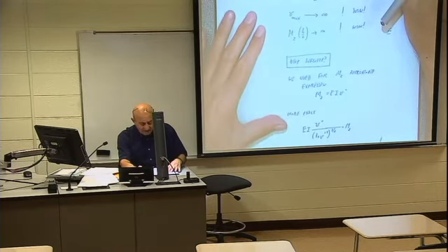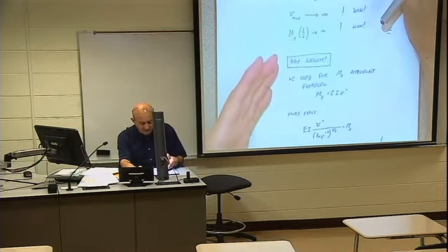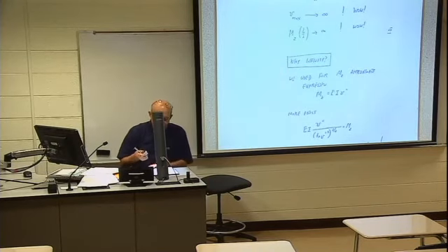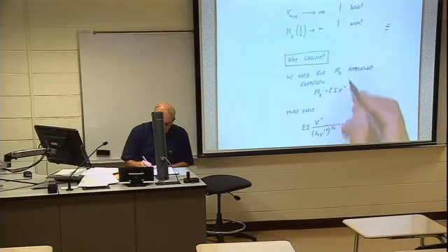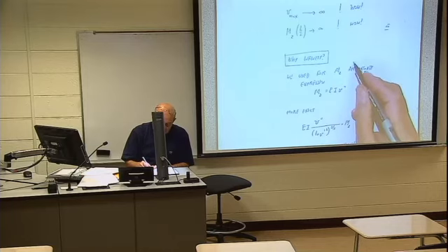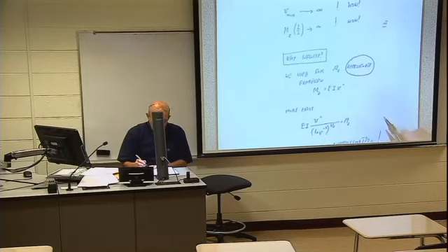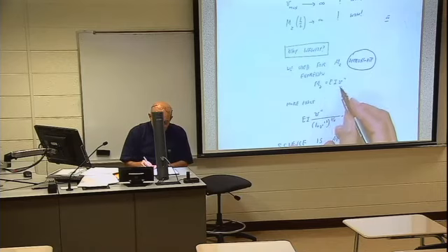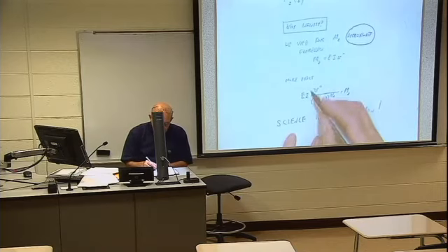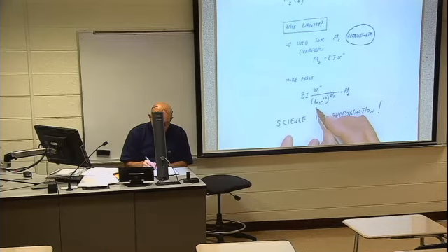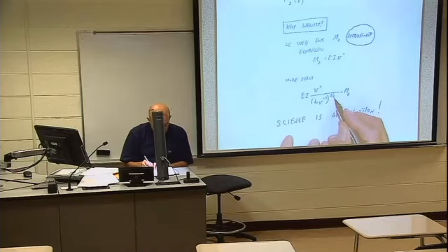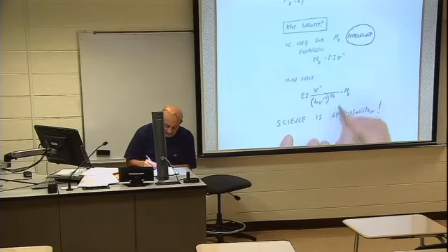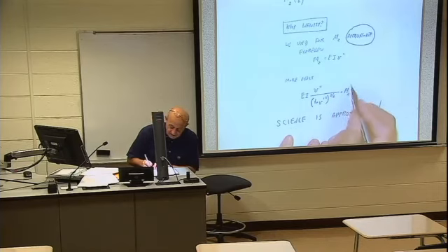Why infinity? Why does displacement go to infinity? Okay, this is because we used an approximate expression for Mz, that is this one, Mz equals EI V double prime. But the more exact expression will be V double prime over (1 plus V prime squared) to the power 3 halves. That is the exact expression.